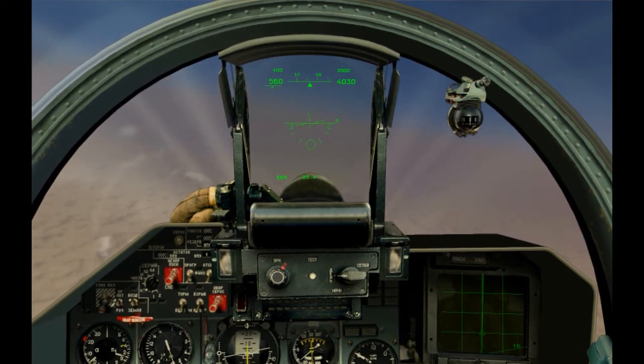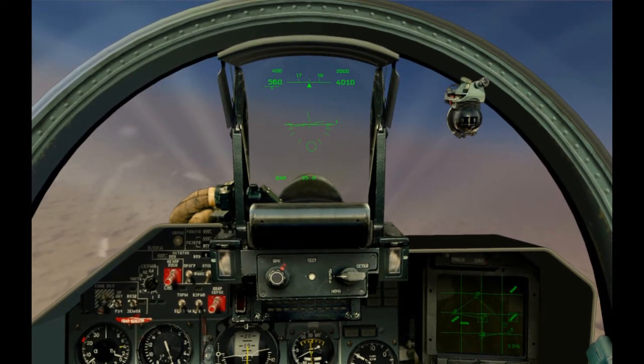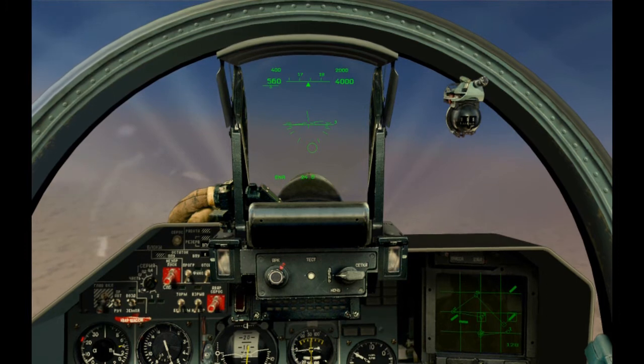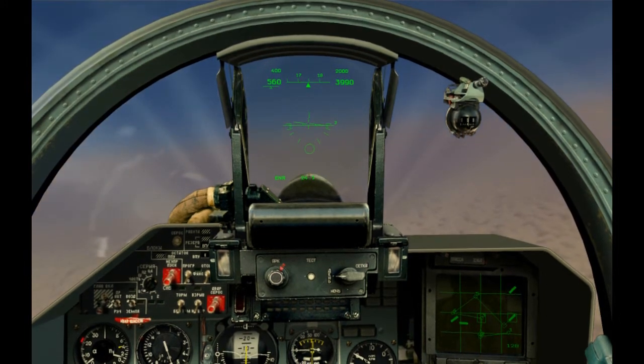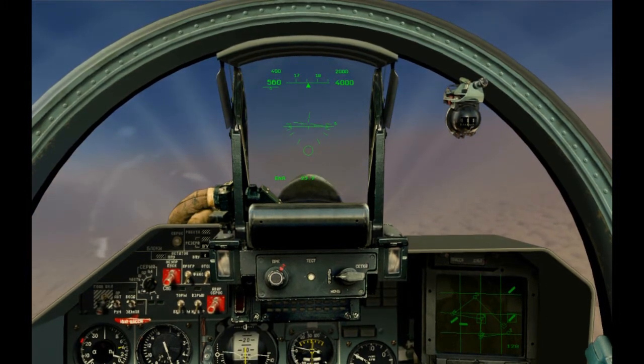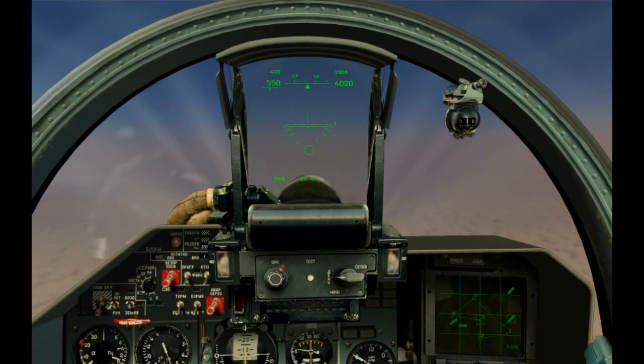Instead of flying my nose into the circle, I'm going to place it just above it, maintaining altitude. By doing this, I still let it direct my turn, but not my altitude. The MFD doesn't distinguish altitude, so therefore I can just fly by that and I won't have to worry about it.